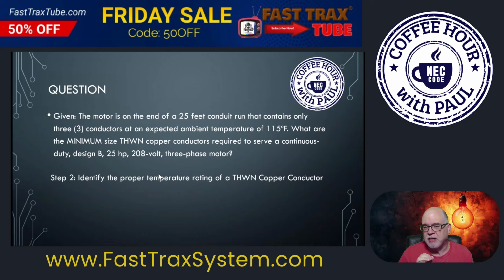So what that means is that it is only rated at 75 degrees C, and we will go verify that. So we do not get the ability to use the ampacity values in 310.16 from the 90-degree column. Why? Because our insulation isn't rated for 90 degrees. It's only rated for 75 degrees. Okay, so that's important to always remember.